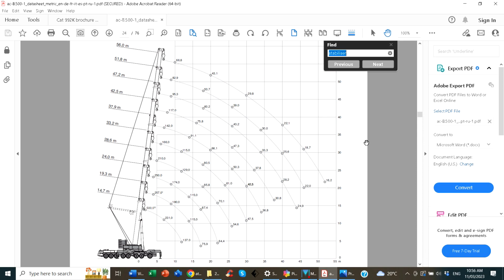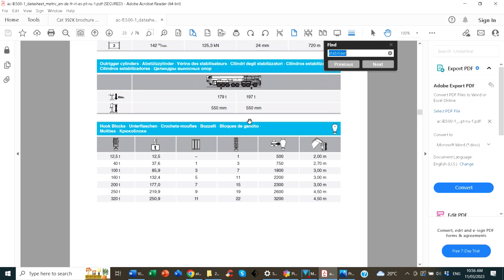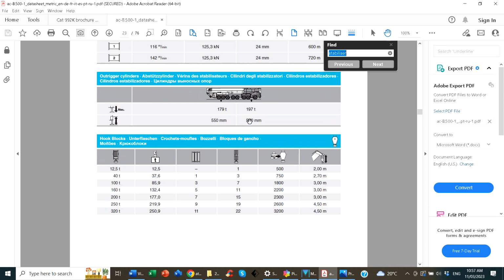Cranes also have graphs like this, quite common. You can work out what the crane is able to carry at certain loads. And a lot of cranes are also pick and carry, where they can pick up stuff and move it around. Not so much in the big sizes. One of the issues with cranes, particularly using stabilizers for stability, is can the ground support the forces from it.